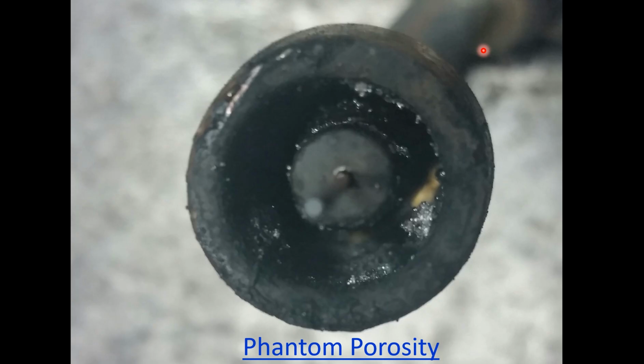Okay, here we go. I want to mention this because I've seen it so many times. This is the inside of a gun that was reamed about 10 parts ago. And there's a reamer. The robotic guns have a reamer that when the gun comes over, it clamps it, goes up and cleans the inside out. Sometimes it'll shoot a little bit. The really good ones will shoot a little bit of air out to make sure it blows all the junk out. And most of them just do the ream, let the stuff fall out, and then send it over, and it puts a little bit of spray on it that both cools and coats the nozzle a little bit so spatter doesn't stick to it as easily.